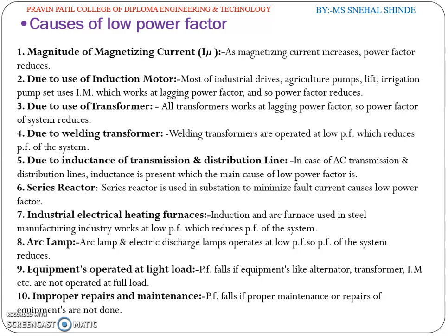So power factor of the system reduces. Equipment operated at light load: the power factor falls if equipment like alternators, transformers, induction motors are not operated at full load.